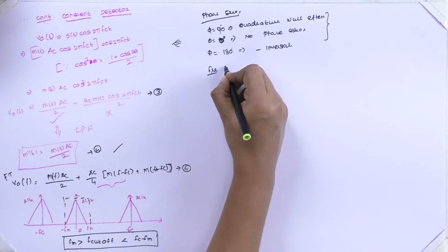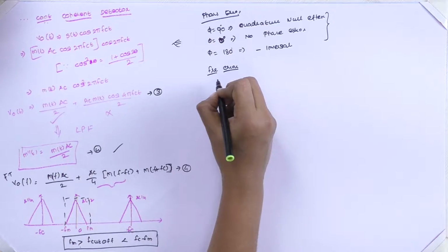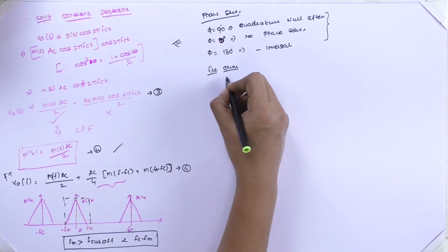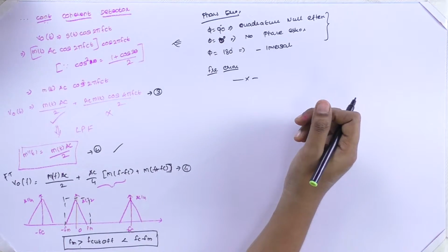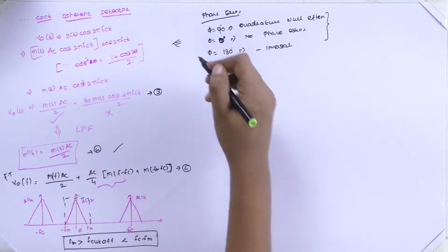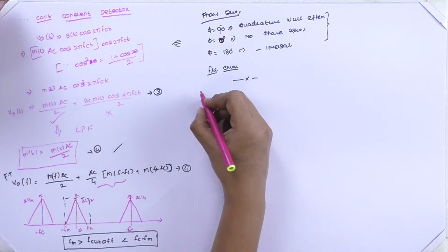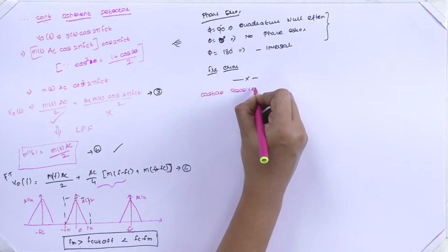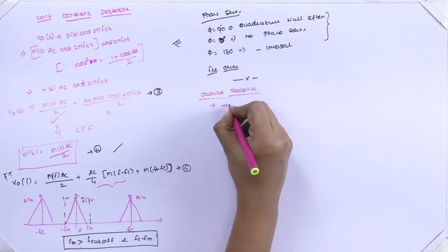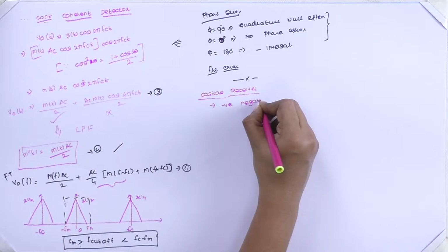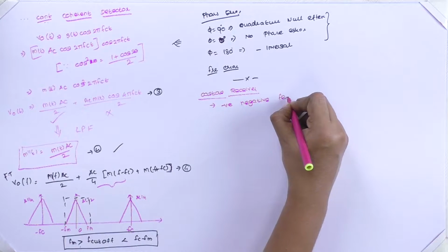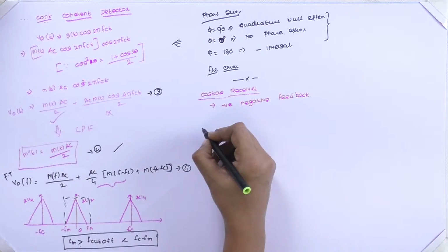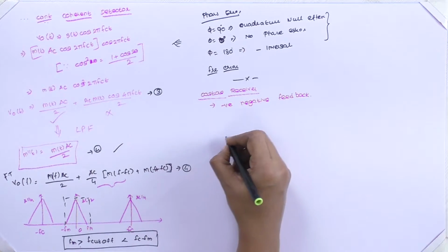If we have a frequency error in the local oscillator, then we'll have either an overlap or we may end up in a situation of not extracting the signal, which we already discussed. Now we are going to see the second one, the Costas receiver. It uses a negative feedback system to suppress the carrier. We'll see the circuit diagram first, then we'll refer to the working.